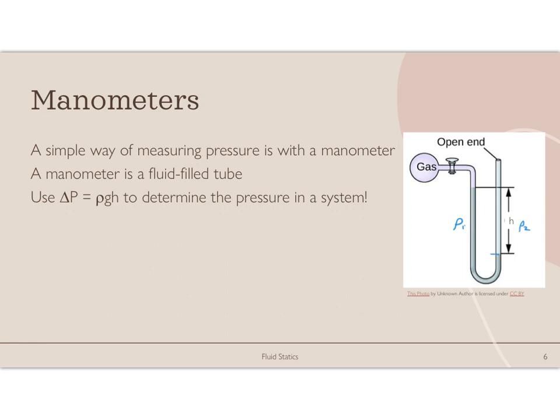And so, whereas at this point the pressures are all the same, we can call that P naught. The pressure here and here are not the same because there are different fluids in there. And the way we're going to use this is that we can simply look at the pressure on one side, which is going to be the pressure on the other side plus rho g times this delta h that we are observing in the difference in the height of the two legs.